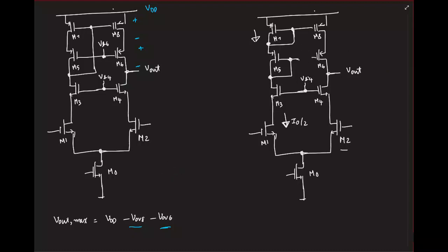So this is the circuit we have. So here, what is V out max? So that will be limited by which transistor now? M5 has no issues, right? Its gate and drain are connected. This is M5, its gate and drain are connected, no issues. So if V out goes higher and higher, what transistor will start to cry?